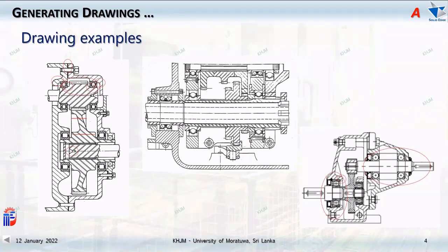I hope I can make it a bit thicker. You see that you have it over here, but you don't have it here, right? But it is fixed from the other end. And also you can see there is a small plate-like thing here. Can you see over here on this particular place? So when you place snap rings and other things like this, make sure those things will either touch the outer ring or the inner ring, but not both. So this is almost fixed from this side.